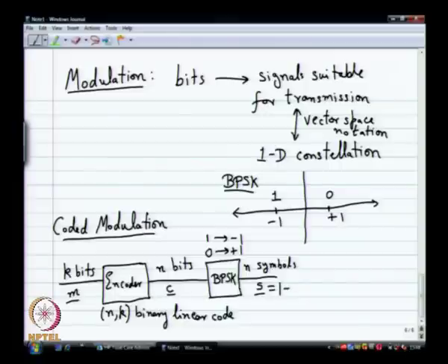Write it as 1 minus 2C. Of course, it does not make any sense in the binary field, where 2 is 0 and you will not get anything. So you have to imagine now that these 1s and 0s are actually integers, and then you do 1 minus 2C, you get minus 1 and plus 1. It is just a simple shorthand notation to represent BPSK. It is not crucial, but it simplifies some notation later on.